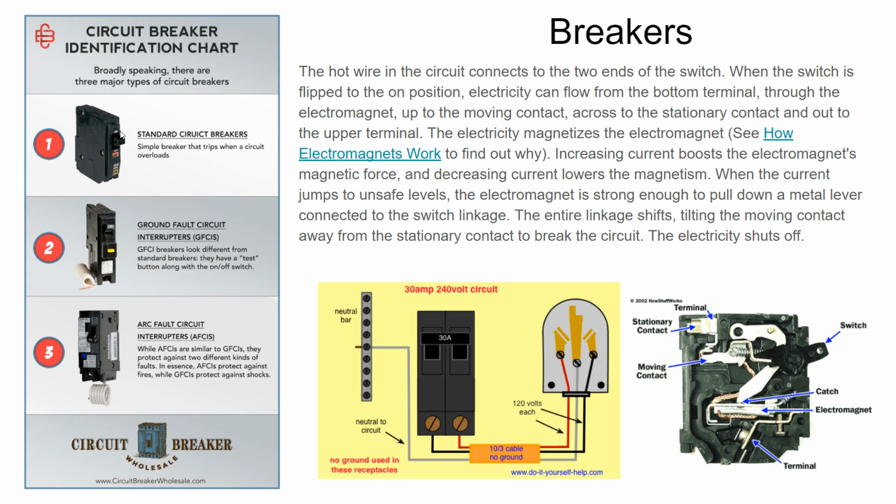But on the flip side of that, it protects the circuit. If that flow becomes too much, if those appliances are trying to draw too much energy off of that circuit, it shuts off. And that's what this is down here. This shows the internals. That contact, if it becomes too much, it will trip the circuit, break the connection, and save everything theoretically on that circuit.